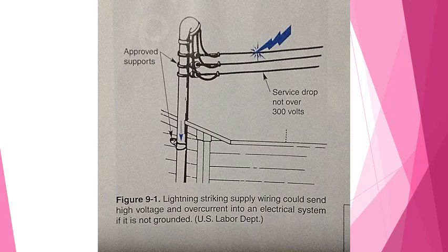Voltage could be in excess of several thousand volts. In a system designed to carry no more than several hundred volts, the damage would be substantial. Without proper grounding, the high current related to the high voltage would create so much heat that conductor insulation would melt. Surrounding structural materials could ignite and burn.